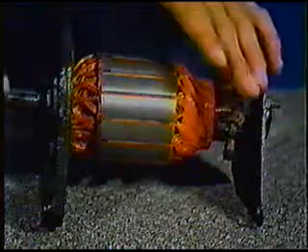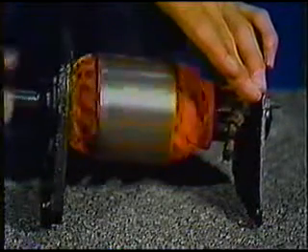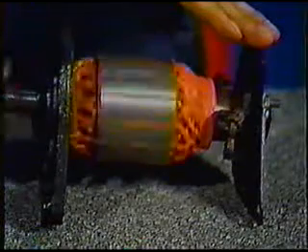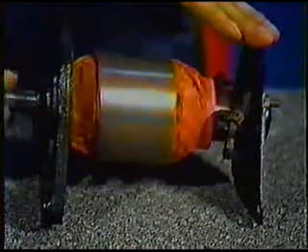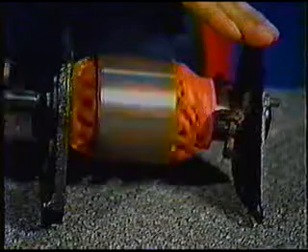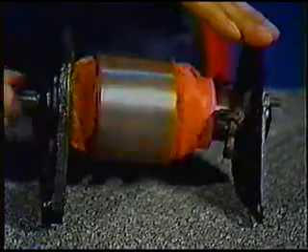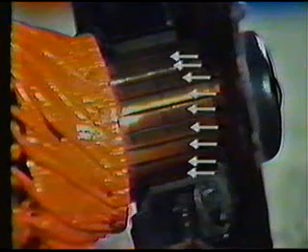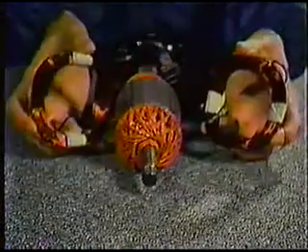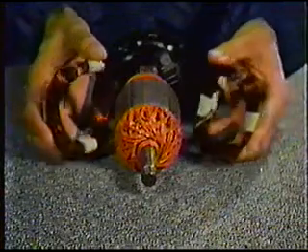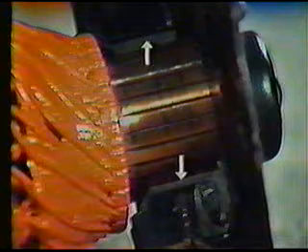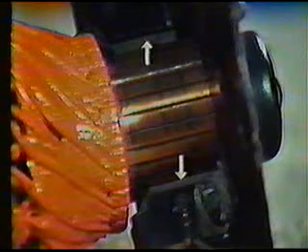The armature of the generator is supported on bearings at either end to allow it to be rotated. As the armature rotates, a small amount of electricity is being produced in each pair of windings and is transmitted through the brushes. By using many segments in the commutator, multiple brushes, multiple conductors, and multiple field windings, the output voltage is smooth and efficient because there are always two segments in contact with the brushes at a given point in the generator's rotation.